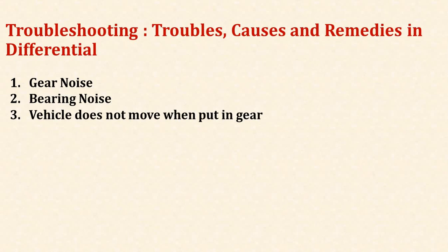Then insufficient or poor quality gear oil, where we have to replenish or replace as the case may be. Then in bearing noise, another cause is broken bearings on axle shafts. Remedy: we have to replace them. And if there are damaged bearings of the rear drive pinion, then again the remedial action is to replace that part.